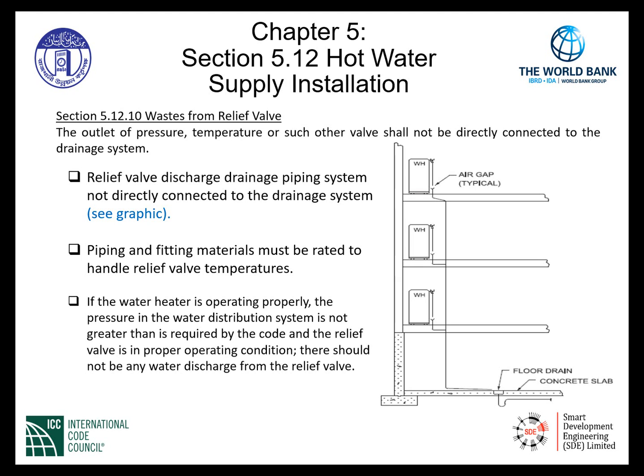The piping and the fittings of all these materials must be rated to handle the relief valve temperatures. So when you see this out in the field, we must verify that the piping is adequate to handle the elevated temperatures. If the water heater is operating properly, the pressure in the water distribution system is not greater than it is required by the code, and the relief valve is in proper operating condition, there should not be any water discharging from the relief valve.